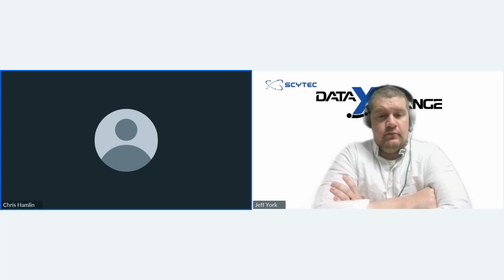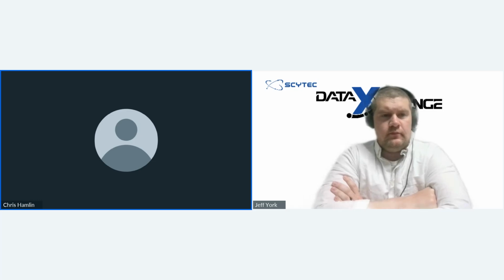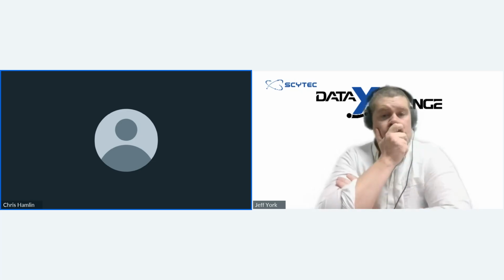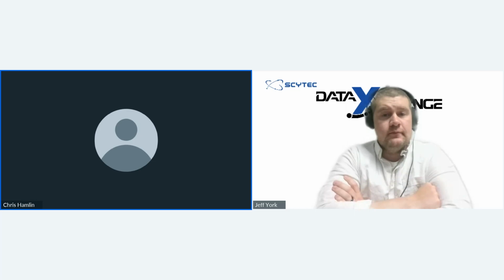One of the big popular ones that's popping up is people want to record the feed rate override and display that in the RTV view. So we can actually get the numerical value coming back from the machine. If it's at 100% and it's just running normal, we can record that 100 into the on-screen RTV view and display that. If someone's turned that feed rate override down and they're running it at 60%, 80%, you can display those values live, again with very little latency, on the shop floor.